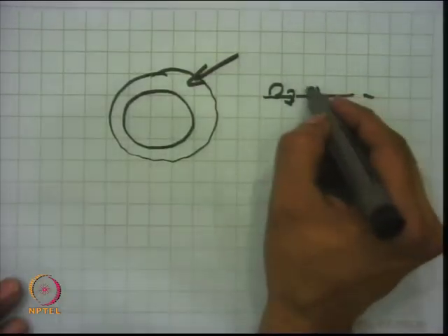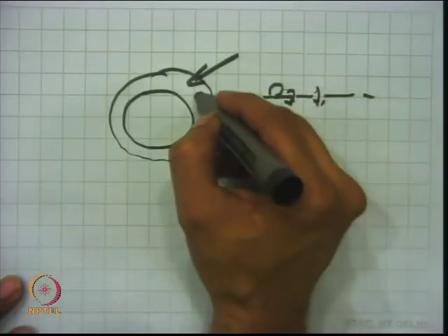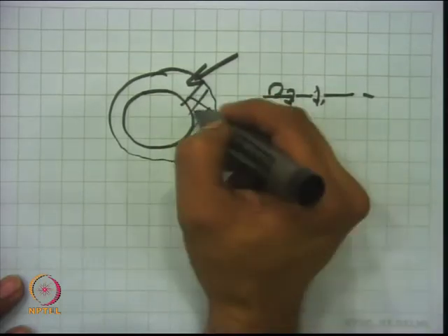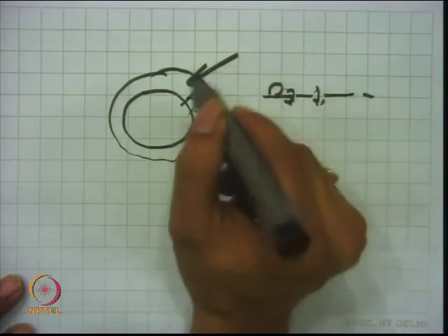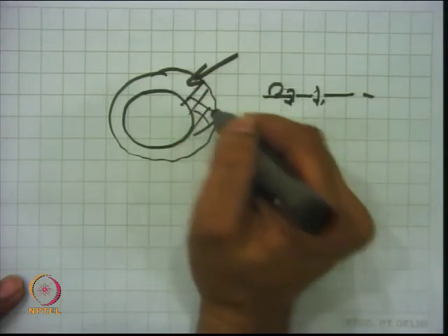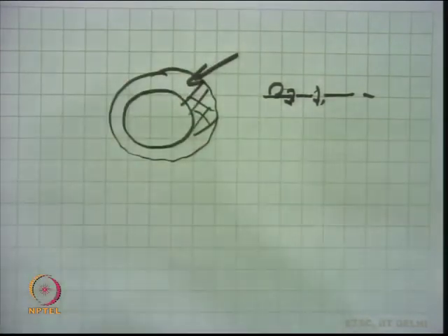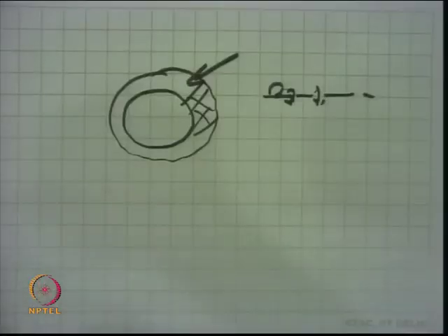So, there will always be a kind of concentration difference at the surface of the solid. Suppose it is only partly covered and this is a bare surface, so here is nothing. It means this surface is not being utilized, because the gas needs some liquid for chemical reaction, and trickle bed reactors are mainly mass transfer controlled, a kind of channel reactors which I was talking about, or wire net type reactors, where now monoliths can also be a catalyst for this purpose,